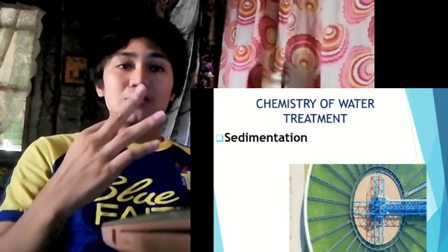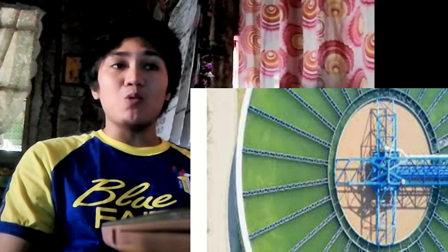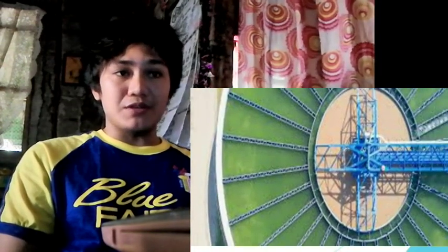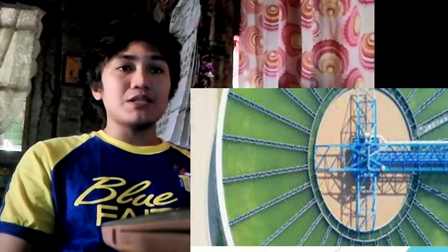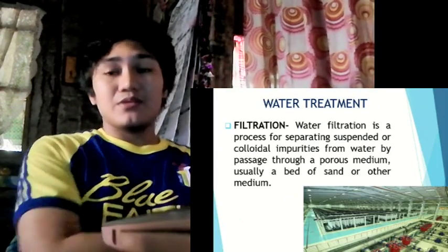Type 3 sedimentation, or zone sedimentation. The particles are at high concentration, greater than 1000 mg per liter, such that the particles tend to settle as a mass, and a distinct clear zone and sludge zone are present. Zone settling occurs in lime softening sedimentation, activated sludge sedimentation, and sludge thickeners. Filtration.